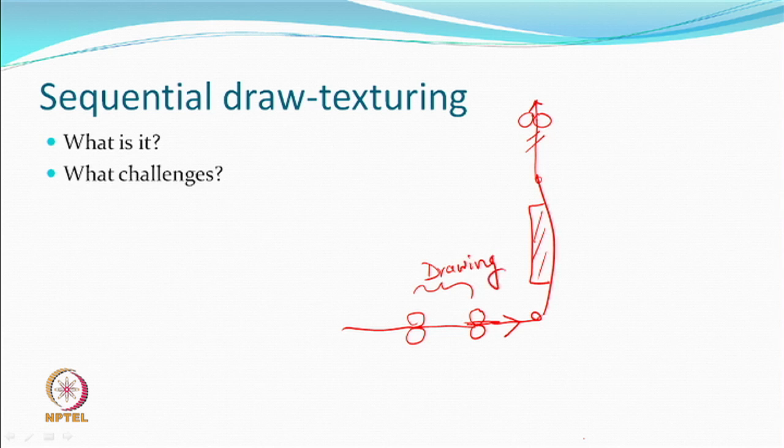If this is what you do, it is a sequential process. First draw and then texturize, but on the same machine. This was not difficult to do, because the only thing you had to do was add another set of rollers, running at a speed lower than the number 2 set, while the number 3 set would be exactly the same as whatever you were doing. So, I said this is easy to do as long as we believe that we can handle the DOFs, and then this particular thing could be done.